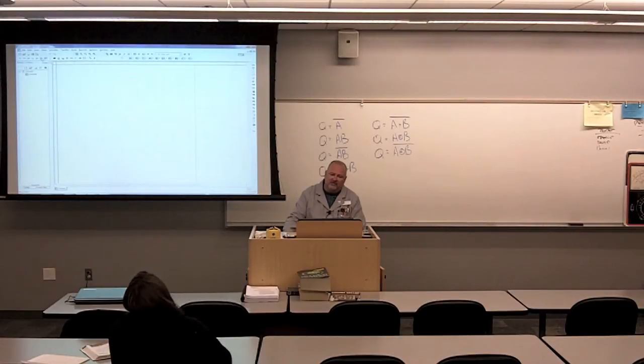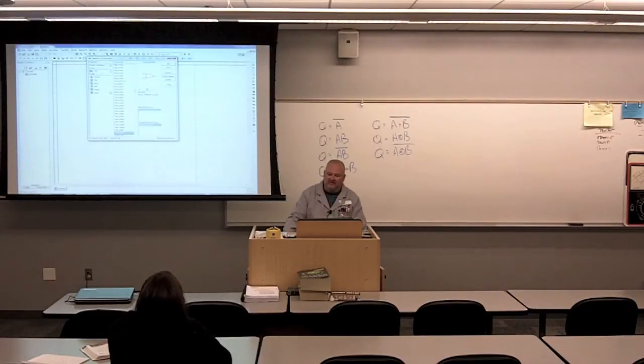So let me just select TTL. And then we've got a variety of different families of TTL that are available. We have the 74 STD, 74S, 74LS, 74F, 74 ALS, 74 AS. Let's just go here with the 74 LS. And then look at all of the components that are available. Let me start up at the top. Can you all recognize that symbol, what that symbol is? It's a NAND gate. Very good. NAND gate.